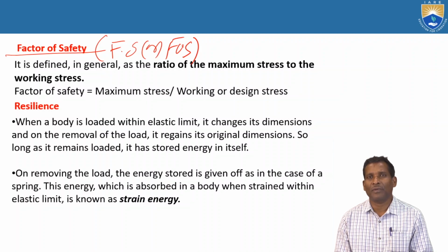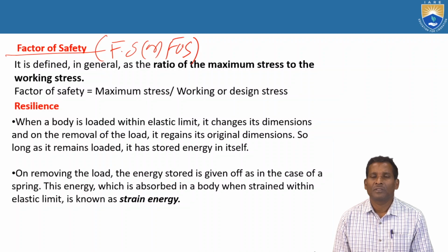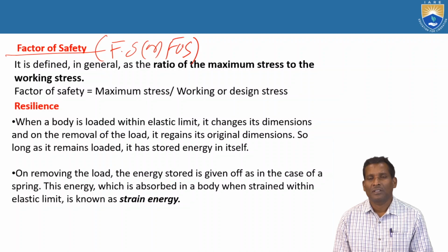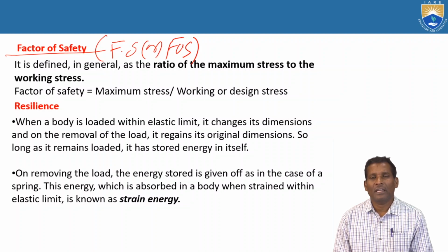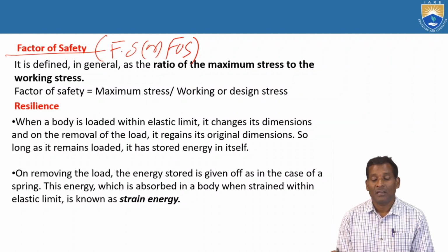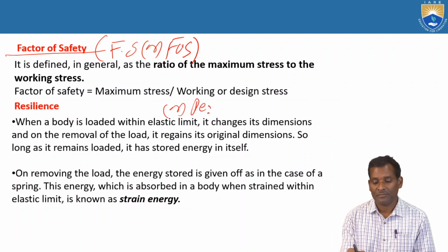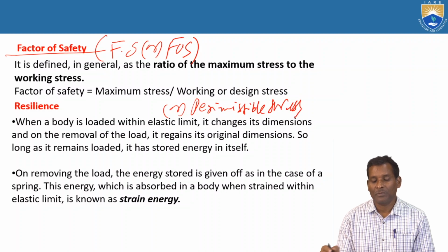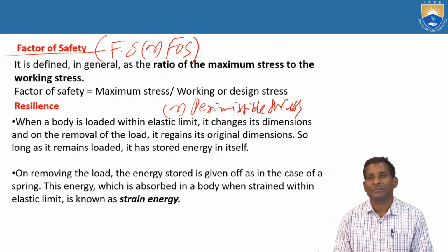So how do you take this factor of safety? Suppose we have the maximum stress value, that is ultimate stress, upon the actual working or design or permissible stress. Then we will get the factor of safety.